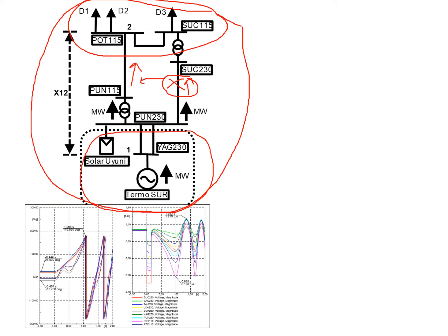is by a high impedance because of the transformer and the line, and produces a voltage reduction in the substation in this area. The voltage reduction and the high impedance of the components result in instability problems of the units of Termoeléctrica del Sur. The stability problem is a loss of synchronism of the units. Here we can see the result of the simulation, and the loss of synchronism is produced in 1 second more or less. This problem will